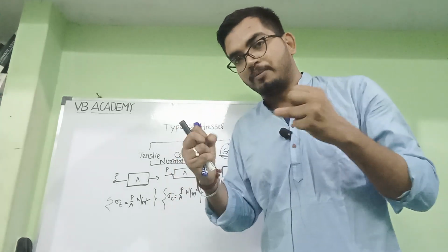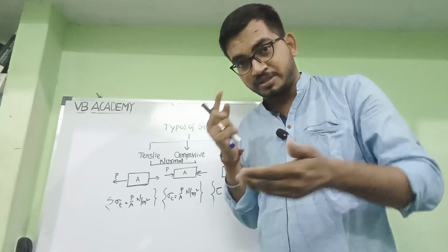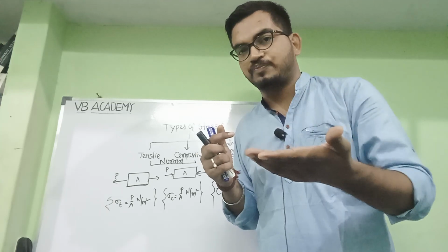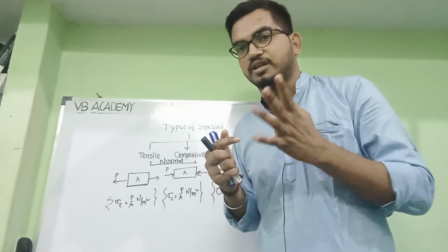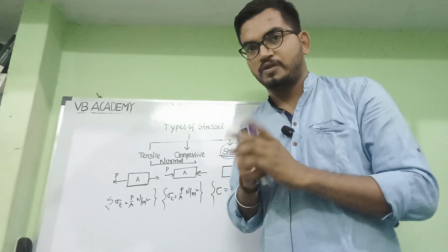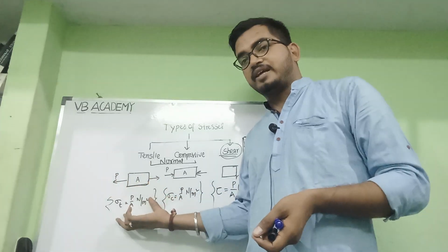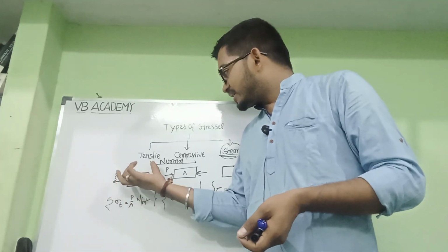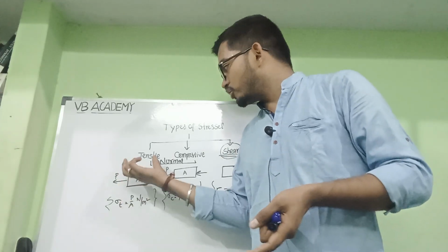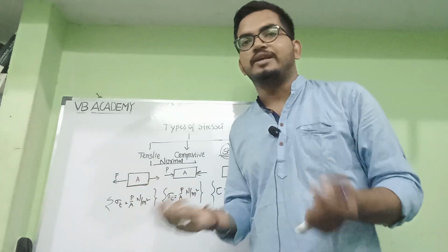Due to this application of forces, the body gets deformed. Deform means a change in dimensions. Initially when the load is not applied and then when the load is applied, the change in dimension with respect to the original dimension is known as strain. As we specified, whenever you apply a tensile load, it develops tensile stress and tensile strain as well.